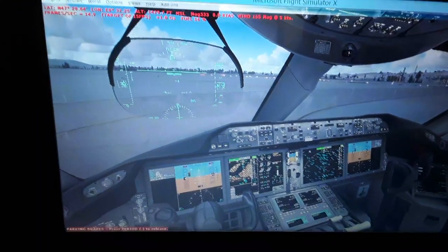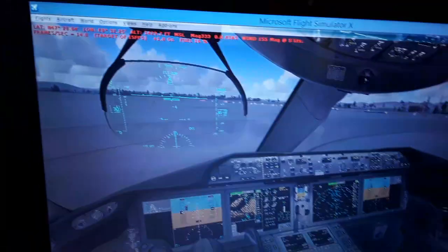So we have also the navigation display. The navigation display displays the horizontal and vertical profile of the aircraft as it flies. You can see the terrain and weather reflections from the weather radar. You can see the red, green, and amber or yellow indication of the terrain around you and also below the aircraft as we fly.